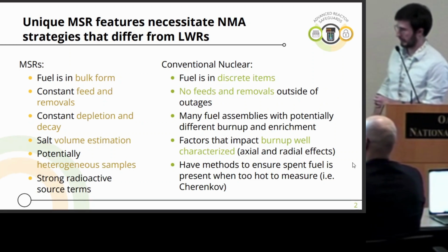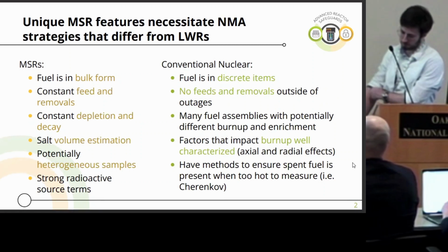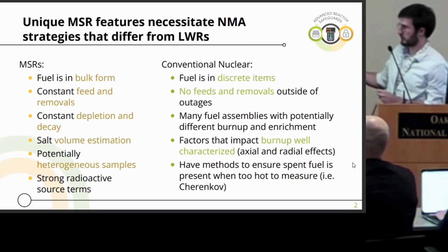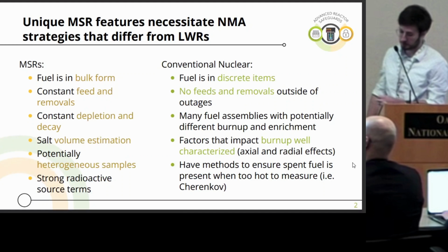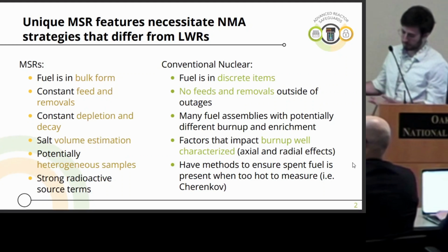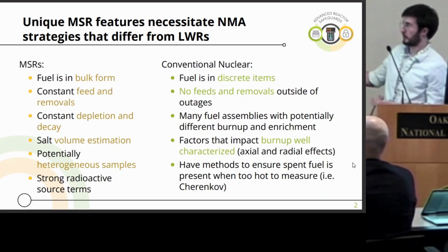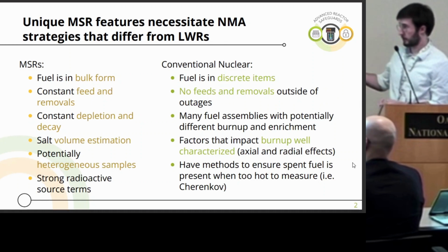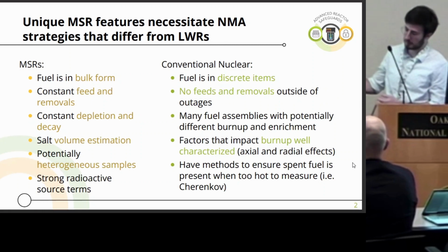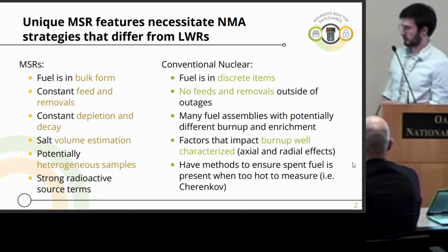Burnup is well characterized. We've studied them for decades. We have well-validated computational tools. But when it comes to MSRs, it's a little bit more challenging, especially on the statistical end, to ensure and quantify your material. Your fuel's in a bulk form. Depending on your design, you might have constant feed and removals. You have constant depletion and decay that you have to account for in process, unlike the LWR, because you could potentially access the process during operation.